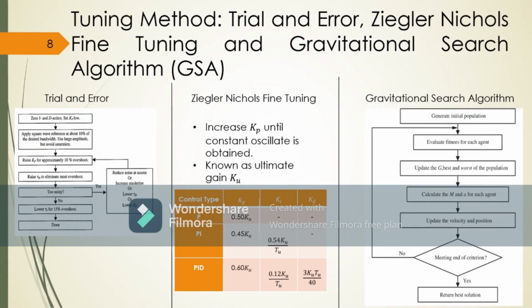The method that I used in this project is the trial and error method. This method starts with shutting down the controller by setting the parameters of the PID controller to 0, and then increasing the proportional gain until the output of the controller oscillates, and then setting the integral gain to a certain value which makes the oscillation reduce. The steady state error will be reduced by changing the value of the integral gain, but will increase the percentage overshoot, and then the derivative gain will be increased until the EHS system quickly reacts to the set point. This step needs to be done once the proportional gain and integral gain have been set to a desired value with minimum steady state error.